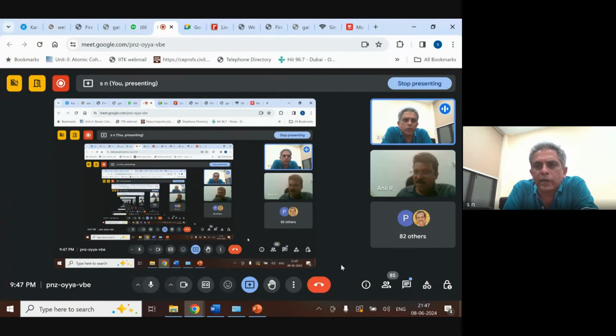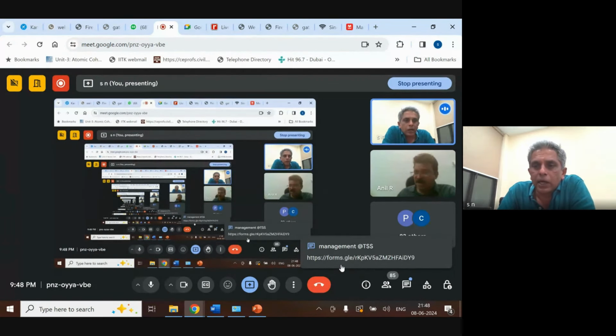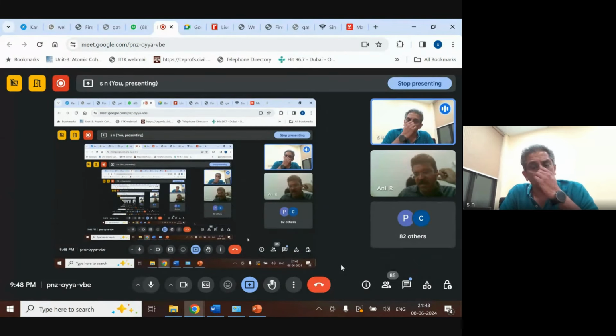Ideally, it should work. That is what I was saying. But again, considering that it is widely recommended across the country, you can try that with a trial patch at least. For all these projects that Kerala is actually encountering, a part of the trial patch can be done without. Not everything, because the contractor is very familiar with using those additives, or is wanting to use that additive. Why don't we just take a chance on, say, 50 meters out of that 100 and do that section without adding any stabilizers and see if it is performing the same way or not. If we have multiple trial patches and enough data, we can validate this thought, or rather the experience that I have had before, and that could be a good way of moving forward.